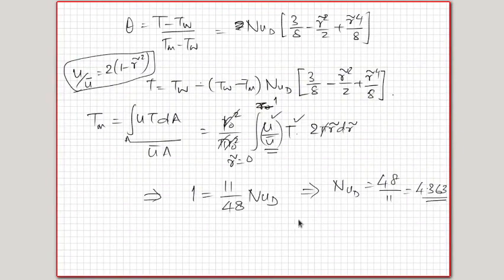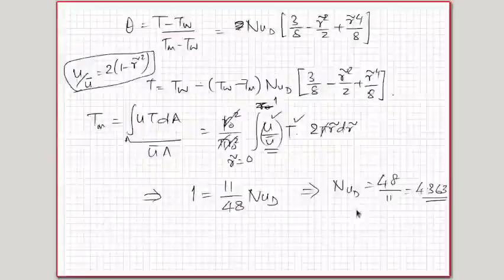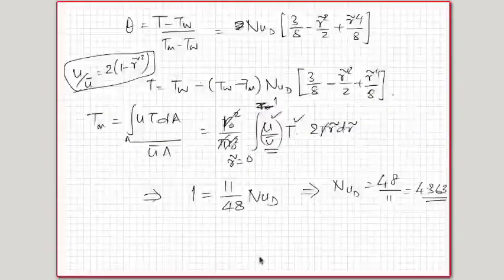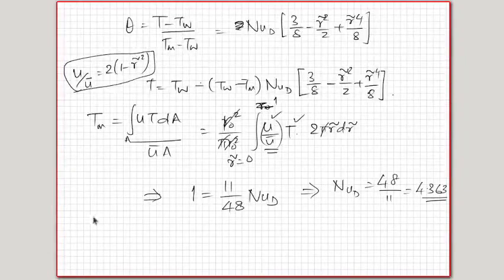Okay, so this is the expression for the constant Nusselt number that results in the fully developed region of a circular pipe in which there is uniform heat flux on the wall. The result would change if slug flow is used.